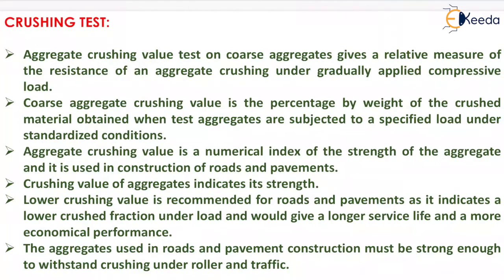Aggregate crushing value test on coarse aggregate gives a relative measure of the resistance of an aggregate to crushing under gradually applied compressive load. Coarse aggregate crushing value is the percentage by weight of the crushed material obtained when test aggregates are subjected to a specified load under standardized conditions. Aggregate crushing value is a numerical index of the strength of the aggregate and it is used in construction of roads and pavements. Crushing value of aggregate indicates its strength.